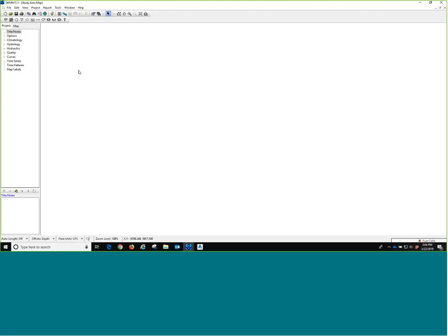I can obviously sketch everything out and run my model, but if I've already gone through the trouble of creating my entire model as a pipe network in Civil 3D, why would I re-sketch the thing out as a schematic? Doesn't make any sense. So I'm going to show you the process of how we take a pipe network from Civil 3D, import that into Storm and Sanitary Analysis, and run our results.